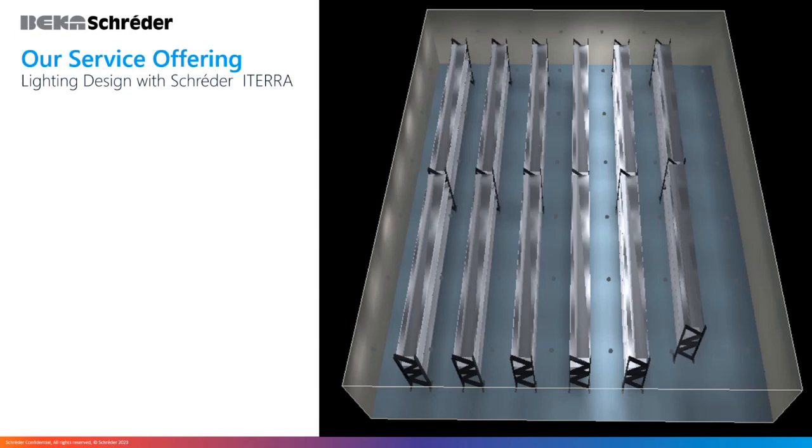In the aisle that's lit up, we measured 150 lux, and in the ones that are dimmed down, the lux level was 120 lux. So you save a lot of energy. If somebody walks into the building or a forklift enters and goes into that specific aisle, only the lights in that aisle will light up and the rest will remain in a dim state. So again, you save a lot of energy.